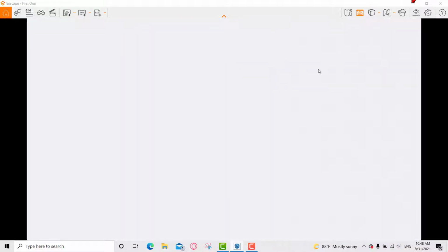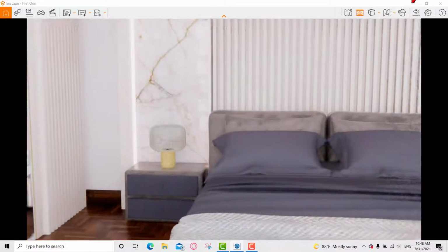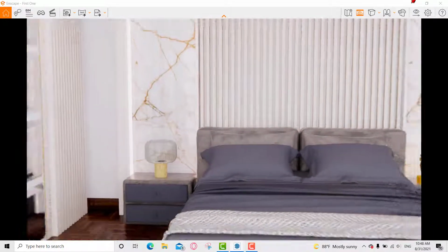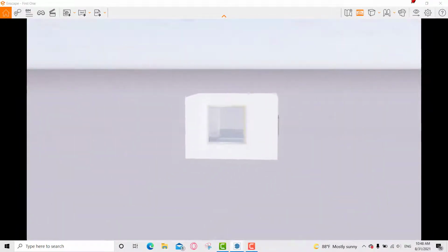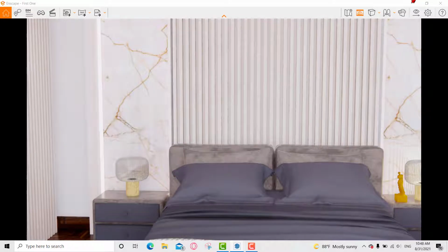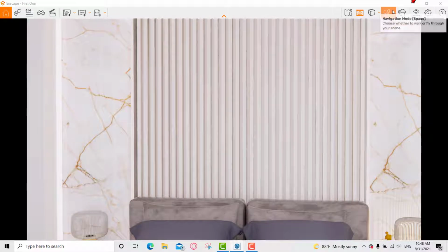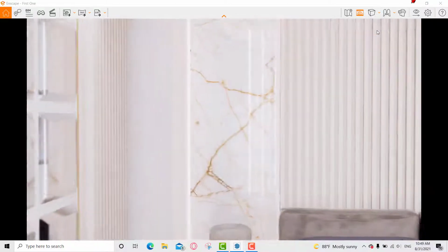Okay, something else I could mention is the speed, shift and the Q when you are moving. You will click shift and control, and then the space to move to walk mode or the fly mode. So if you click again, it will be fly mode, so you will be able to go up and then down, etc.